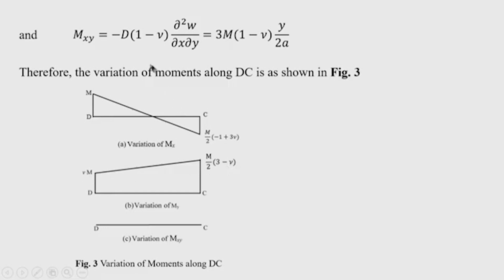But since the torsional moment or twisting moment does not contain any x, when we plot the variation of Mxy along the x axis, it represents a straight line. Okay. So, that is the problem that I have discussed, the special case where the triangular plate is subjected to edge moment. The main philosophy of solution of this type of problem is to take the deflected surface as a function of x and y in the form of a polynomial, such that it contains the equation of the line.